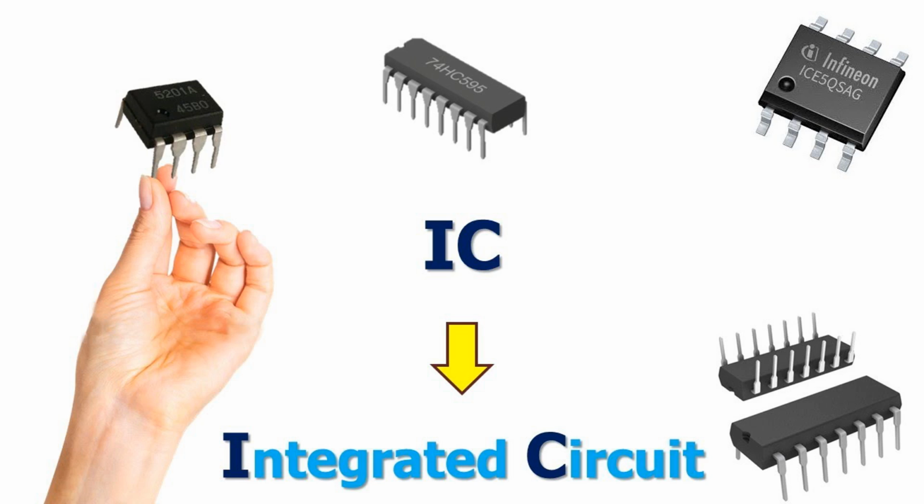Shifting function. Shift register ICs are used to shift data in a serial or parallel fashion. They allow data to be moved from one location to another within a circuit. Serial versus parallel shift registers. Serial shift registers. These shift data bit by bit through the register, often with a single data input and a clock signal. Parallel shift registers. These shift all data simultaneously using multiple data inputs and a common clock signal.